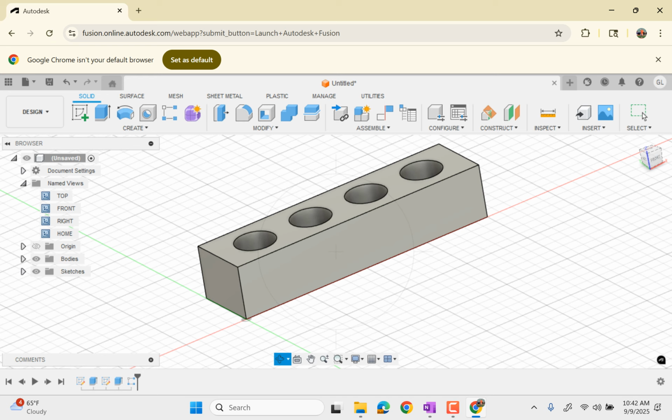And then we'll mirror this extrusion across that construction plane, and it'll take the chunk out of the other side, okay? So that can be another big time saver when you're doing a lot of things, or if you want symmetry of a complicated part.